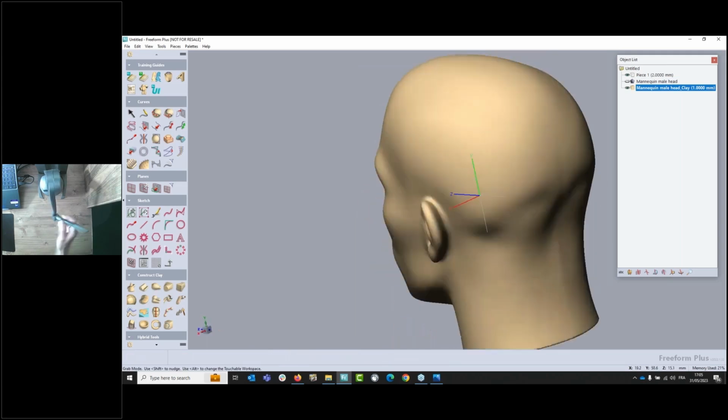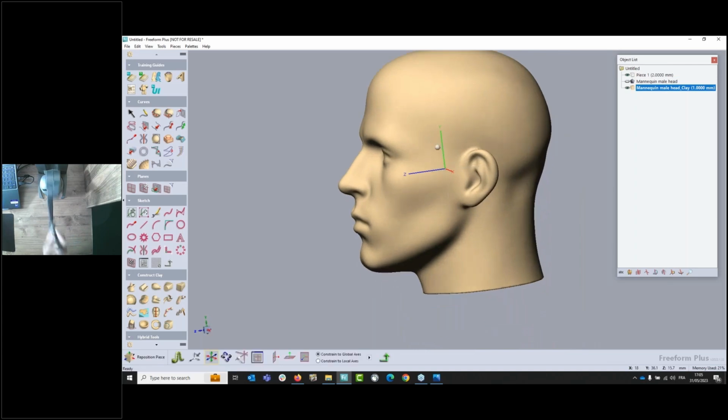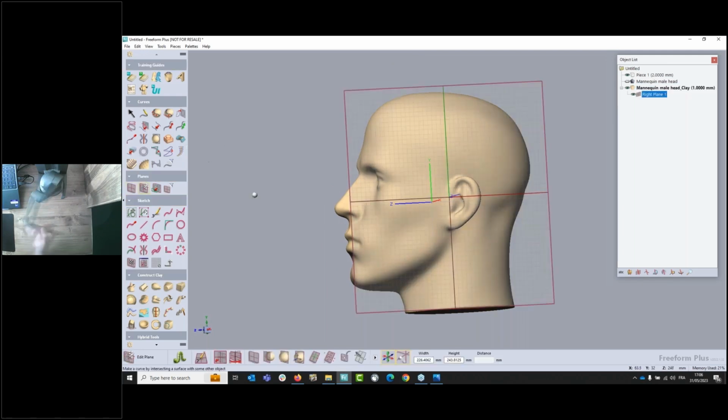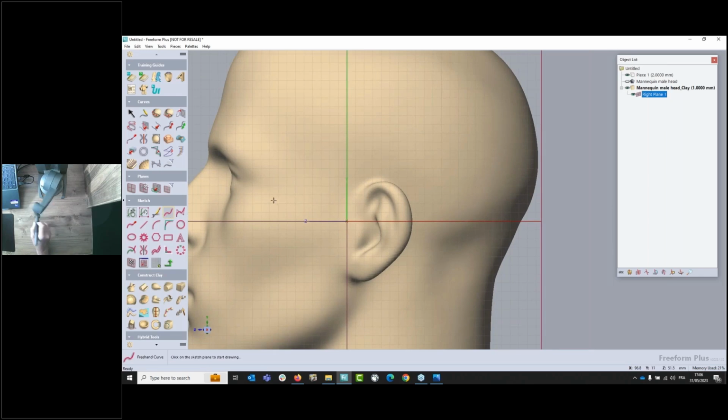So here's my digital clay object. The first thing to do with this, to build my helmet, will be to create a plane to draw the first lines. In my tool palette, I will choose my Create Plane tool. Then here in the Dyna bar, the first button will allow me to sketch on this plane. Then I will draw two things. The first one will be a 2D curve on the plane, just roughly to draw the shape of the head.